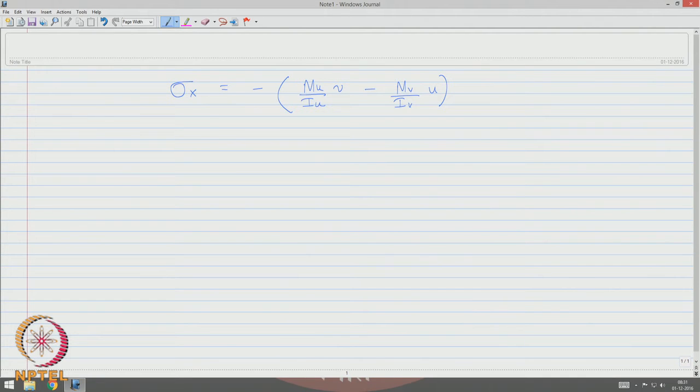We said, for this being the z axis, and these being the u and v axes as located at alpha 1, using the right hand screw rule, the moment will be Mz, which is now resolved as Mu, which is Mz cos alpha 1, positive.